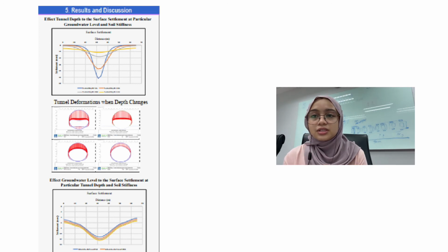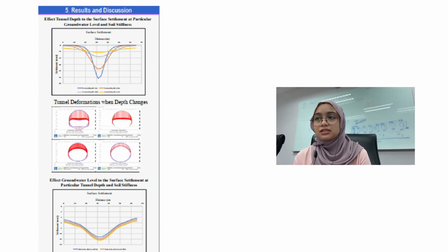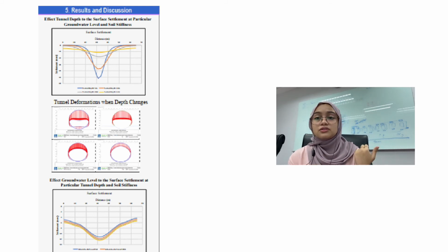at the 32 meter depth, the result of the tunnel deflection is 26.73, and based on the design criteria by MRT, the result has exceeded 25 millimeter.